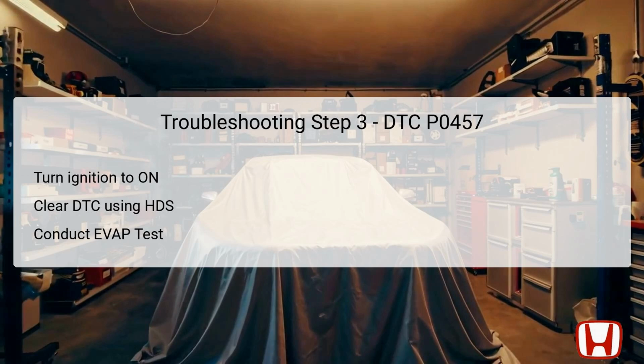fault memory. Following this, technicians should access the inspection menu and select the EVAP test to perform a function test on the system. If the results indicate that the test is okay, it suggests an intermittent failure, and a deeper investigation into potential poor connections at various component terminals should be carried out. If the malfunction is confirmed, further troubleshooting steps need to be initiated to resolve the issue efficiently.